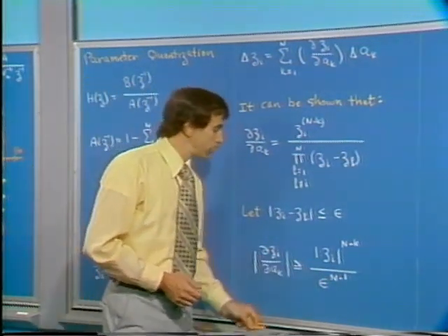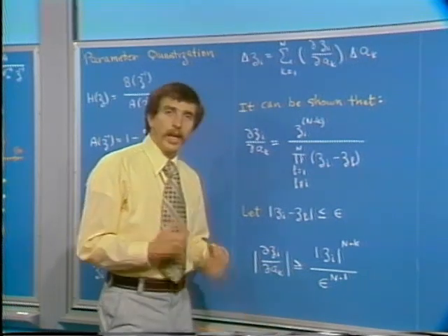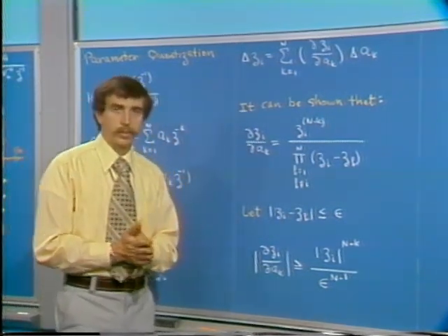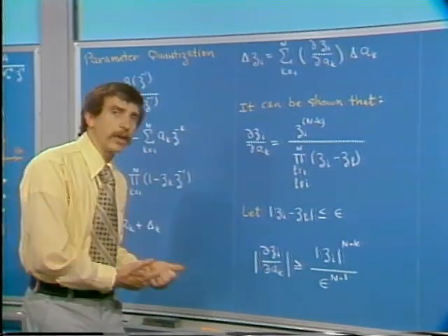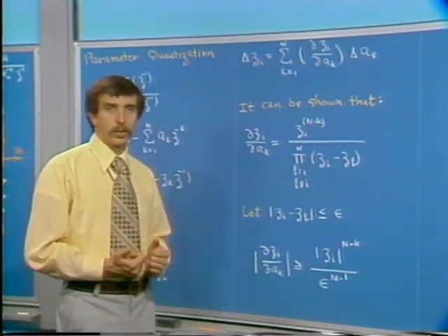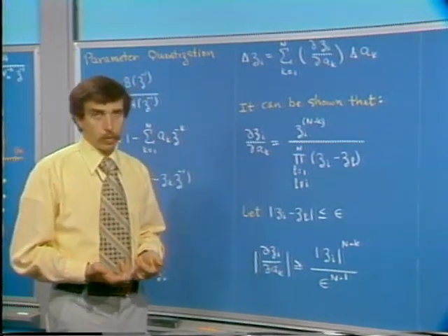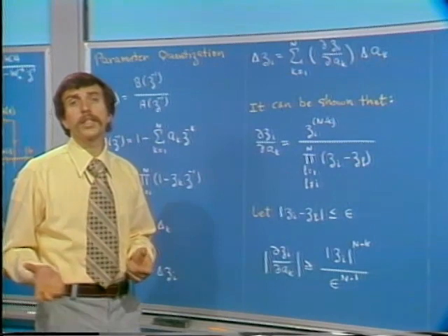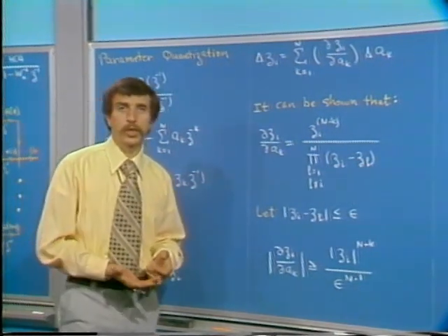So this says that when we implement the poles of the system, it obviously is better to implement the poles through a lower order polynomial rather than through a higher order polynomial. What does this mean in terms of the filter structures we've been talking about?